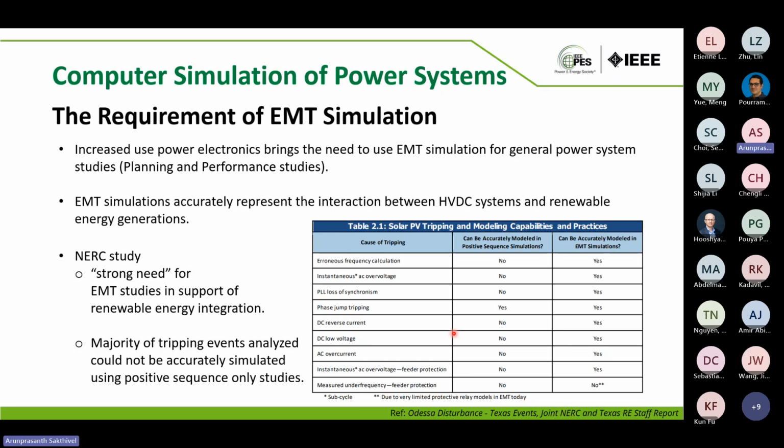And therefore, the EMT simulation is required for general power system studies, such as planning and performance studies. And also, as we know, the EMT simulations accurately represent the interaction between HVDCs and inverter-based generation. So from the NERC study, they strongly recommend EMT studies to be done for renewable energy integration.